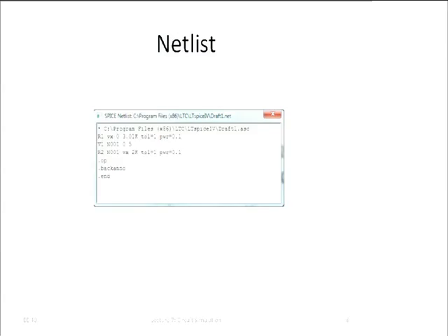Incidentally, internally, SPICE does not use schematic diagrams. Internally, SPICE describes circuits in some other way using a netlist. You can see it actually lists resistor R1, the voltage source, the resistor R2. It tells how they are connected from Vx to ground, and so on and so forth, and gives the values. We are not using this description here in EE40.